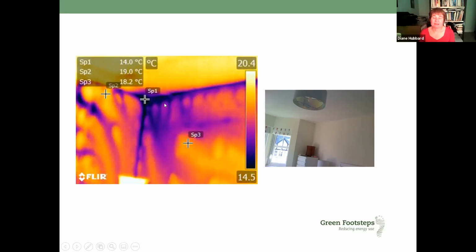So the best idea, if you're going to use plasterboard, is to have a continuous layer of adhesive behind the plasterboard, or that the underlying wall is treated with, say, a paint-on air tightness layer. But that's a good example of showing what thermal bypass looks like.